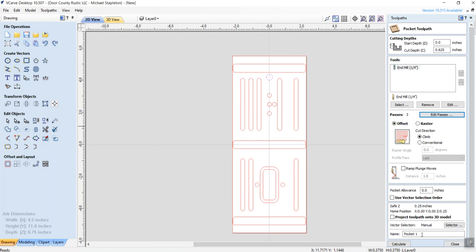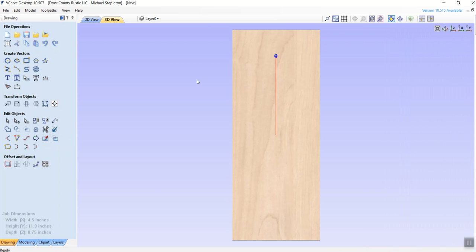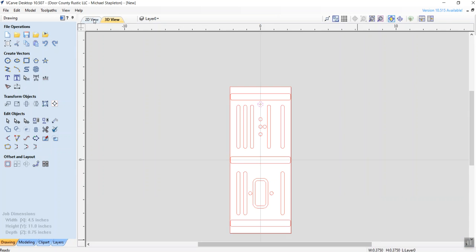And then I'm going to create a pocket or a path named 3/8 inch peg. And then I usually type in 0.625. That reminds me of how deep I'm going in on that one. I'm going to say calculate. I don't bother running any of these tests right away. I wait until later. Now it always goes down to that.